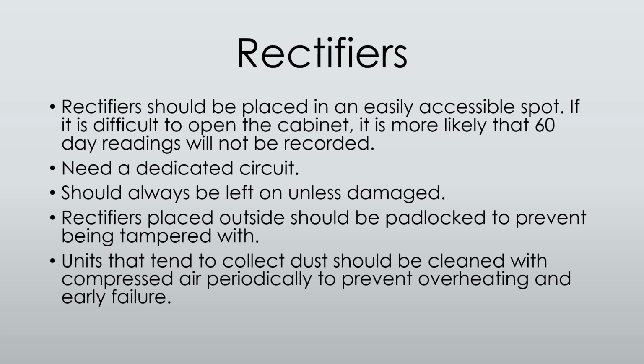Rectifiers should be placed in an easily accessible spot. If it is difficult to open the cabinet, it is more than likely that 60-day readings will not be recorded. I see this all the time. Put them in the back stock room, get a bunch of boxes in front of them. They're installed up high, somewhere awkward. People forget they exist. You have turnover in your building, and the readings never get done. And then a year later, somebody comes by, you have an inspection, and you find it's off, and you have no idea how long it's been off, and you got problems.